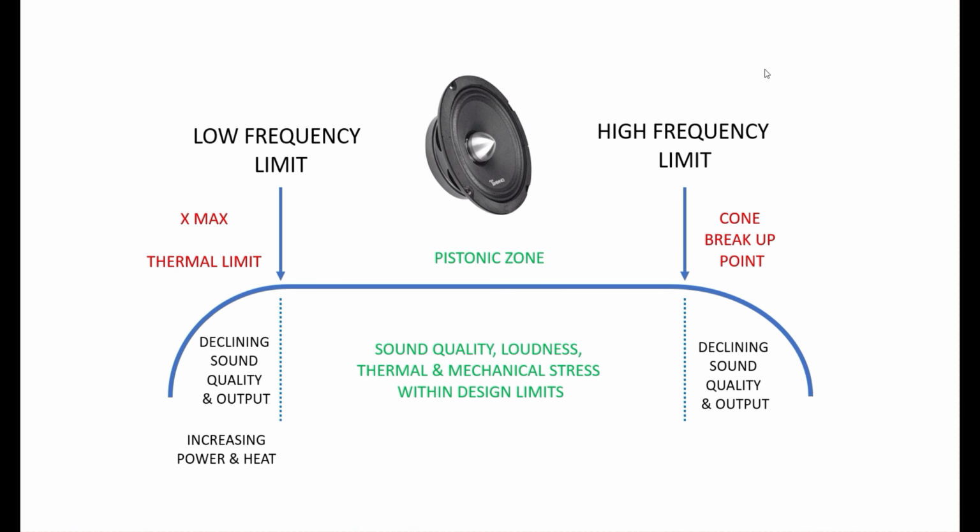They can't handle the power that's required to play that note at a particular frequency. And at the other end, they reach a limit where they can't oscillate any faster to produce a high frequency note, right? They get to a point where the cone starts to break up, and the impedance and that type of thing starts to reduce the output of the speaker, right?